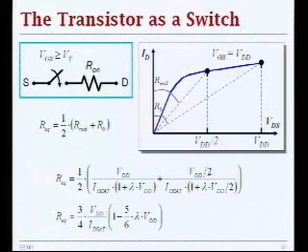Remember the RC network that we talked about in the last lecture? So basically you have an equivalent resistance that is a model of your transistor. That's the driver. And then you have the capacitance that was the load that is presented by the gate in the next stage. So that was the gate capacitance of the next stage. And you can certainly calculate this equivalent resistance of your transistor in an exact way.